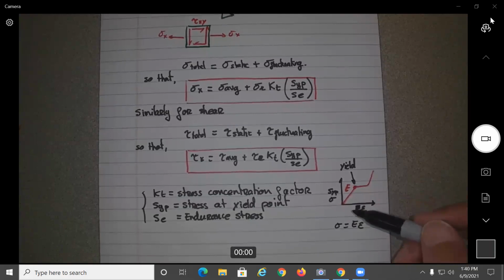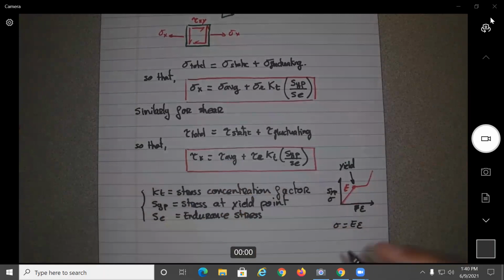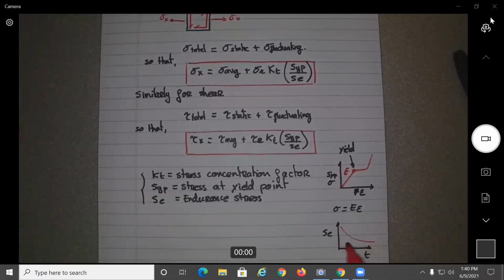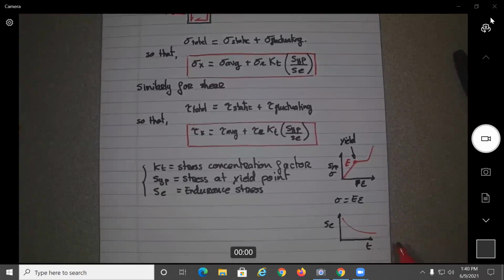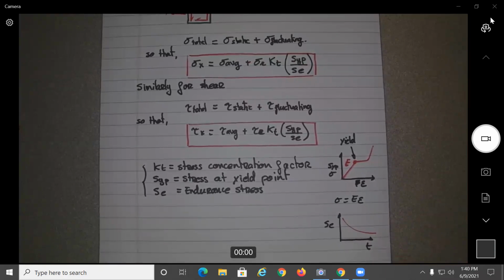Okay, now imagine that you have a piece of metal and somebody is going to start doing it like this. So they're going to have the stress over here as a function of time. And they're going to find out, let's say, as a function of time, when is this going to fail? And they have a curve, whatever. So let's see, how should the curve look? The higher the initial stress, the sooner it's going to fail, no? The lower the value, the lower the value. But this should be all experimental data, right? That is obtained.